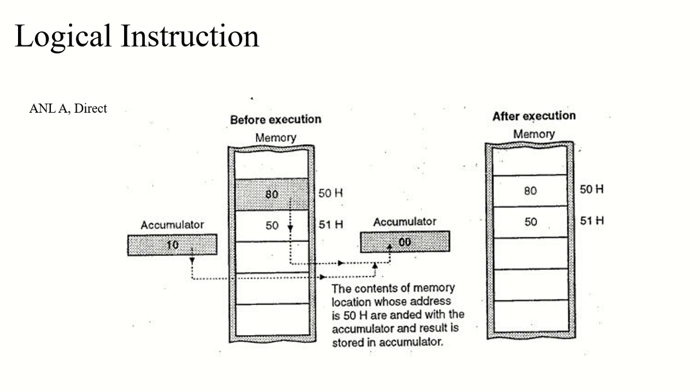When this instruction is used to modify an output port, the value used as original port data will be read from the output data latch, not the input pins. Always be aware of this whenever you are doing practical work or executing it in Keil, that the original port data will be read from the output data latch and not the input. Many people make this mistake while learning, especially beginners.